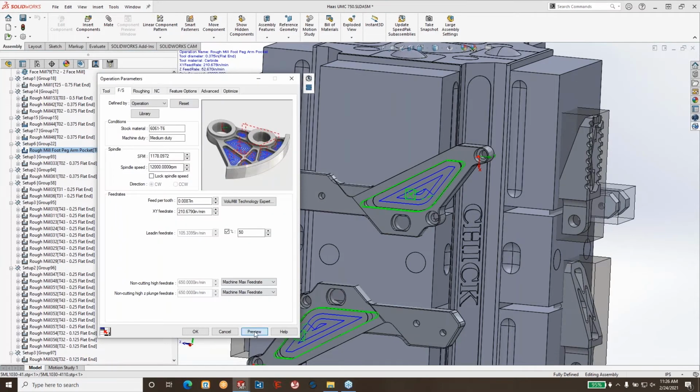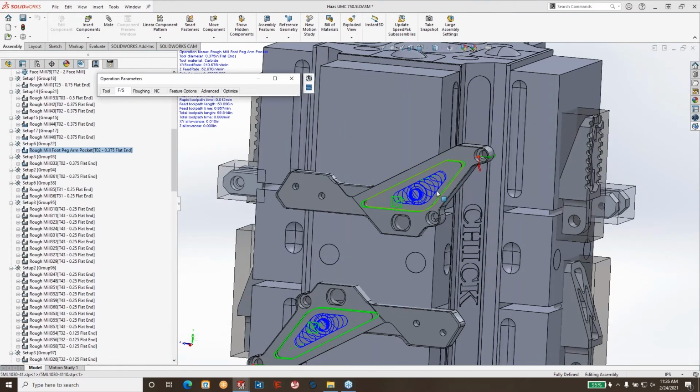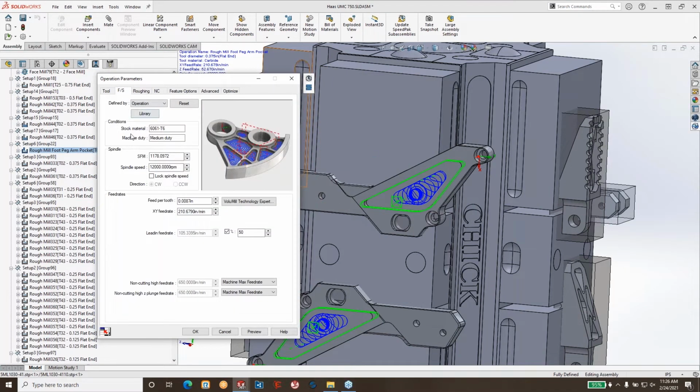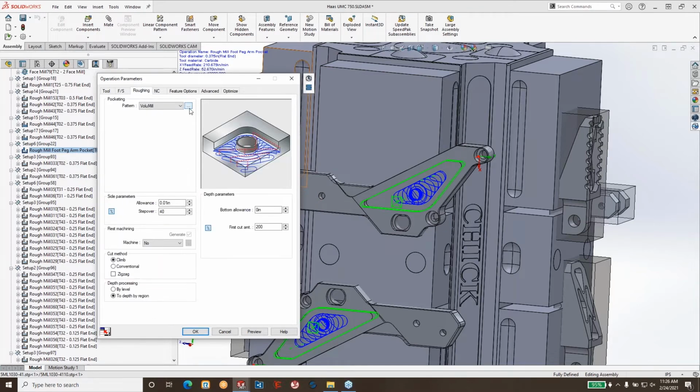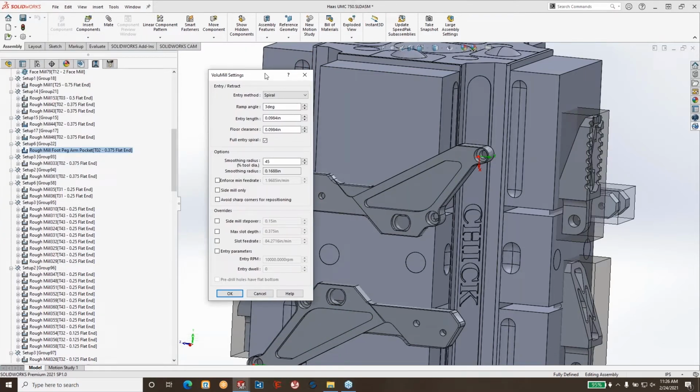That's going to take that tool path. I hit preview, and it's going to go through and rework that tool to go down inside and actually cut all that out. So you can see it gets off the top a little bit. So inside here, Daniel, a lot of people, when you start programming, they might miss this. There's 3 dots right here. And inside those dots, it gives you more control, right? You want to spiral, plunge, ramp in, whatever you want to do, right?